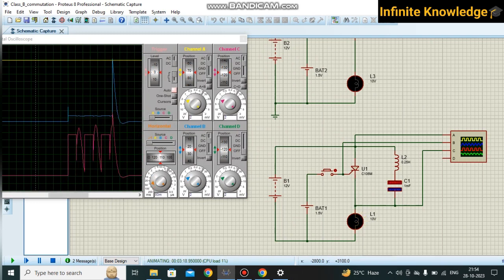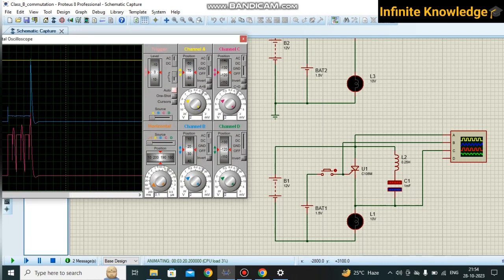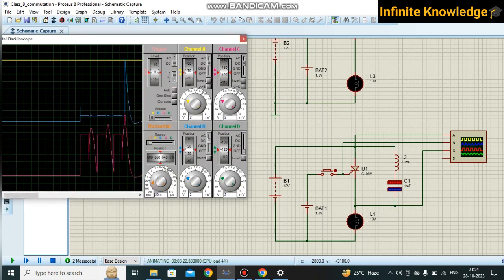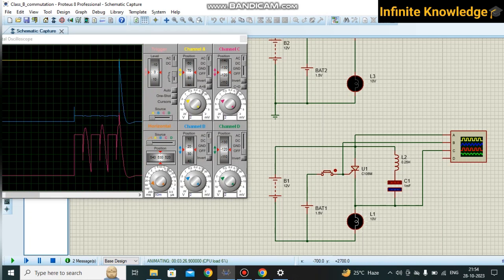Here, if we use a digital oscilloscope for better understanding, whenever I press the switch, it's very crystal clear. For a certain amount of time you are getting output voltage, and this is your capacitor charging and discharging cycle. And once your gate pulse is completed, actually this is happening three times because the time duration for switch on and off is very high, since I am manually switching on and off.